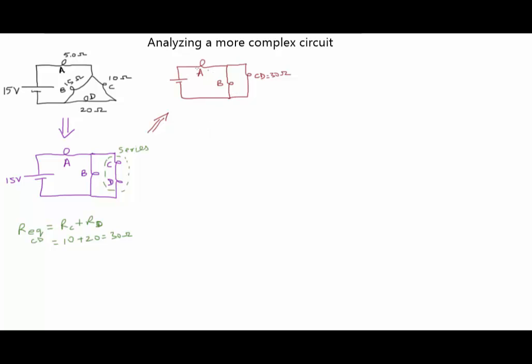All right, so now let's reanalyze this and see which 2 pairs of resistances we can conclusively say are in series or in parallel. Once again, A and B are not in series because of the junction, and they're not in parallel because they don't have the same potential drop across them. But now we can see that B and CD, this new combined resistance, are in parallel. So my next step will be to combine B and CD, realizing that they are in a parallel arrangement.